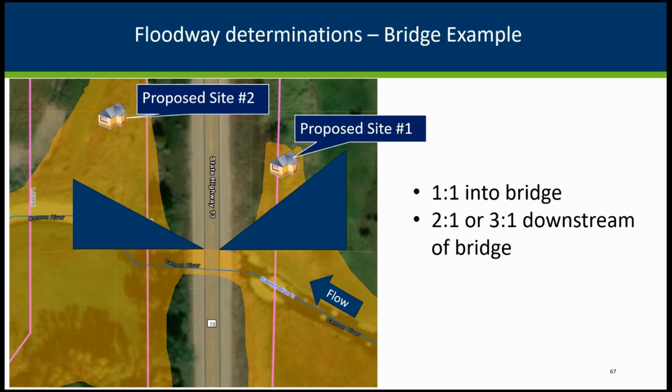Hey, Jeff, we had a comment in the chat that this only applies if you don't have a lot of water going over the road, or the majority of the flows are going through that culvert crossing or that bridge crossing. That is a very excellent point. Thanks for that clarification. Yes, it only applies if all the water is going through the bridge. But if you have water going over the bridge, then those expansions and contractions are not relevant to that bridge opening anymore, or you need to make some additional judgment call to make sure you understand where that velocity risk is.